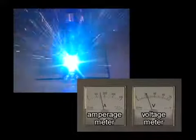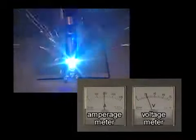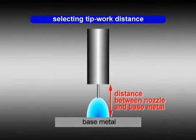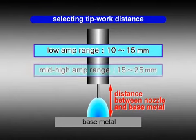One of the most important things to remember when handling the torch is to keep the torch tip height constant while welding. The welding operator monitors the distance between the nozzle and base metal to keep the wire stick-out length constant. The distance is typically 10 to 15 millimeters for lower amperages and 15 to 25 millimeters for amperages over 200.